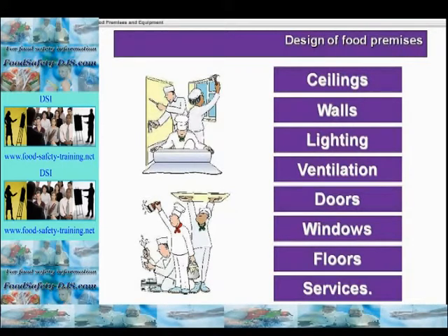Also, the use of grease traps should be considered, but you must ensure there's a flow from clean to dirty. Although in recent times grease traps tend to be frowned upon, and what companies tend to do now is to use biological grease dissolvers, i.e. bacteria and other little organisms that actually feed off the fat and reduce it into things like carbon dioxide and water and other harmless substances, rather than have grease traps, which could attract pests like rodents onto the property.